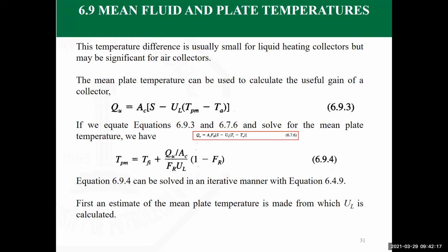I remember when we were working, we had a brand of solar collectors that originated in Italy, but there is a factory producing it in the United States. So the efficiency expressions were given as functions of the inlet temperature for those in the United States, and in terms of the mean temperature for those in Europe. That was one of the issues we had to take care of while doing our estimation of the efficiency and the required calculations for the number of collectors and so on.